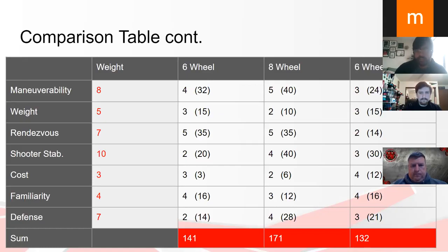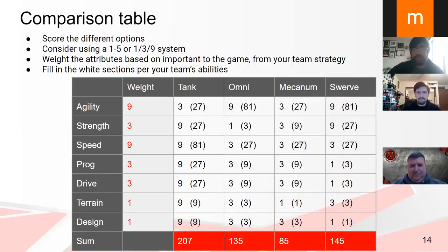Because you asked nicely, I am going to point out that if you're ever not sure about your team's ability to consistently build stuff or your relative inexperience, and you're looking at your preseason trying to figure out, okay, we're worried about the drivetrain, we really want to make sure that it's good and we can move on to other parts of our robot, just get the kit of parts drivetrain. It's a really effective drivetrain. It really does not lose out super hard compared to other tank drives, a custom tank drive.